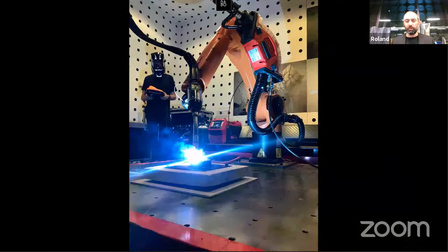And so we've begun to look at wire arc additive manufacturing, or WAM. And so this is a metal printing technique, which is using a MIG welder, which is mounted on a multi-axis robot. Because in MIG welding, the arc is made by the filament, the wire, which is fed through the welding torch. When that connects, it closes the arc and melts the wire.